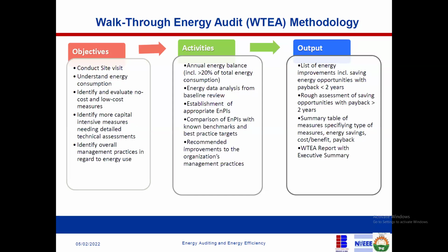So how do you conduct a walkthrough audit? You conduct a site visit. You understand the energy consumption. You identify and evaluate no cost or low cost measures. So you can agree with me that some of the measures I'm recommending now might not be costly. If you are not using good windows, or if your windows have openings, I can recommend you make sure your windows are airtight. Okay, those are low cost.